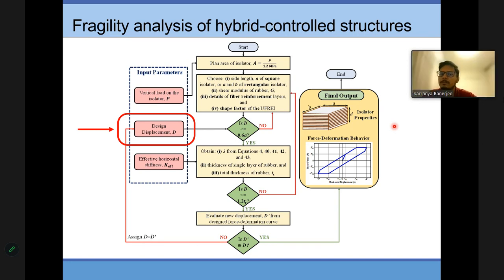So I believe a simple design procedure based on the design spectrum is more useful. Yes, sensei. So the reduction of response by TMD can also be modeled like equivalent damping.